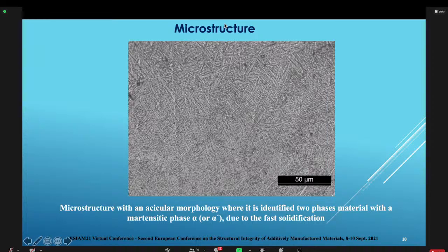No, Torsten. Indeed, the analysis that I have presented is only for the Paris regime. This is the first analysis in SLM materials, but I have done the same analysis in aluminum alloys, in the 6082 aluminum alloys. In that case, you are right. In near threshold, the shear parameter, the shear K, is very important, and generally crack closure increases a lot. Okay, thank you very much.